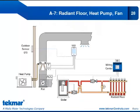Our last application, this time the accessory relay will be operating the fan instead of the dehumidifier or the electric strip backup. Our first stage of heat is still the radiant floor, so we have the W going to the wiring center. Second stage of heat from our heat pump with the Y relay. O for the reversing valve, and now my accessory relay will operate the fan.